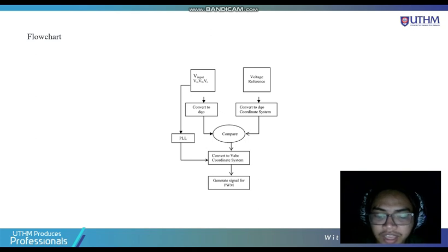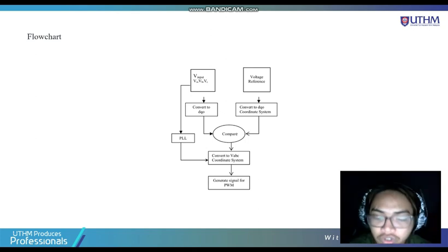The difference between the reference and the load voltage will cause an error signal to be generated. The value of VSI through the PWM control unit, which can be seen in the circuit, is adjusted after the error is minimized by the PI controller. So the inverter will be triggered by a PWM generator, which will produce the desired magnitude, phase, and frequency, in order to inject the missing voltage at the transmission line.